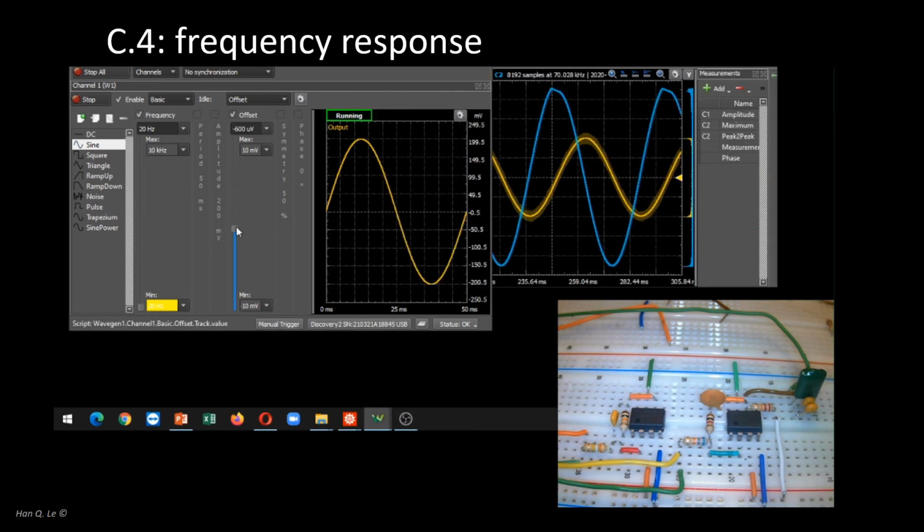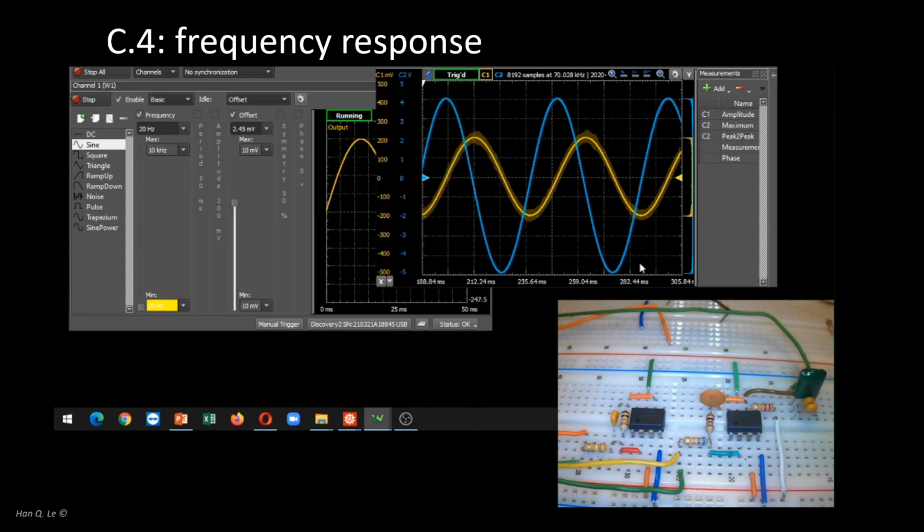Prior to the scan, the output indicated a high DC level, causing the output signal to be intermittently saturated. Adjusting the offset helped solve this problem, which was important as the data would not have been valid otherwise.